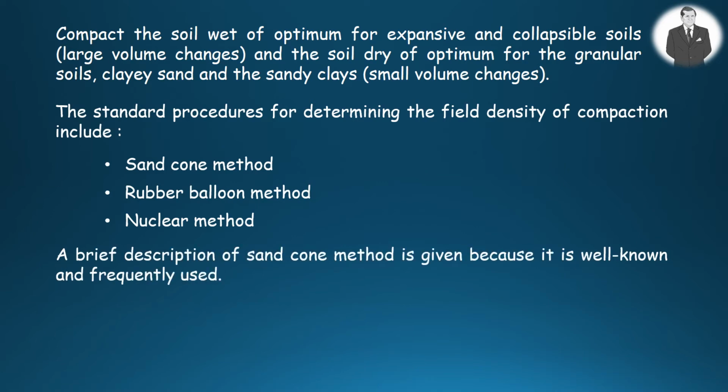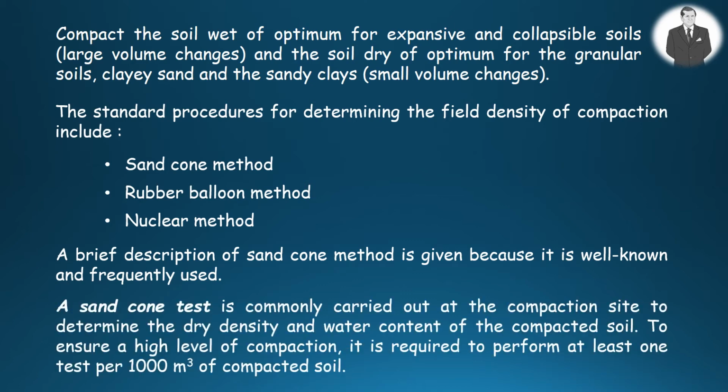Since the sand cone method is very well known and widely used, a brief description of it will be given. A sand cone test is commonly conducted at the compaction site to determine the dry density and water content of compacted soil.